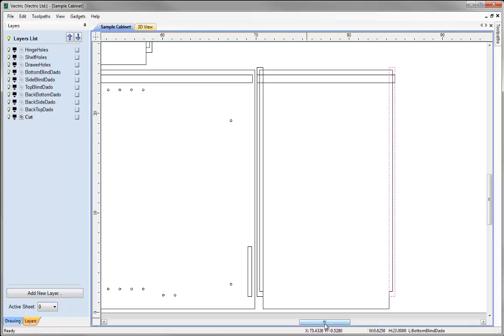And what we can do is simply try and work out what type of toolpath we're going to apply. Now I know that I'm going to be using a 3/8 of an inch end mill tool for the dados, so in decimal format that would be 0.375. Now, because the width of this vector isn't more than twice the diameter of our tool, we could just use a profile pass to machine out our dado here, as we could just do a profile on the inside of these vectors, and that would do the same as what would be achieved if we did a pocket, and it would also be a lot more efficient than doing a pocket toolpath.